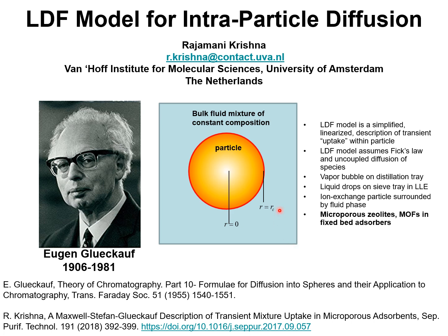When a spherical particle of radius r sub c is exposed to a bulk fluid mixture whose composition is maintained constant, the constituents in the fluid mixture will diffuse inside the particle. The LDF model is a simplified linearized description of transient uptake of the components within the particle.